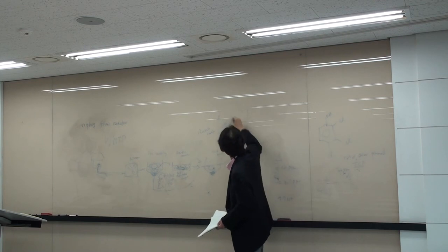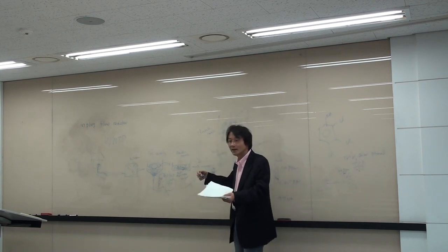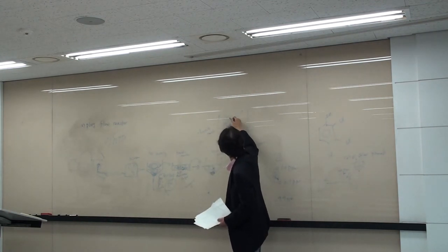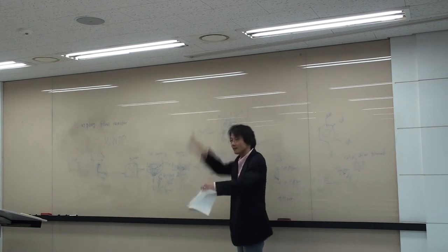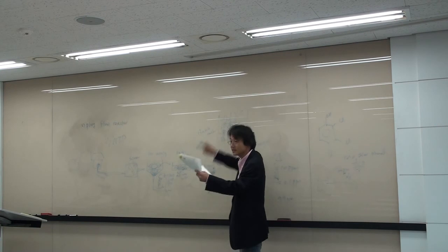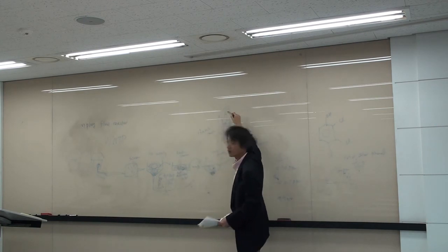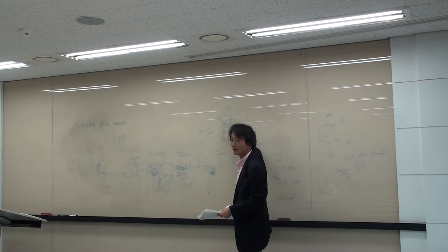Or you can put in a mechanical agitator, a kind of paddle on the surface. It is just like this, so it can agitate the water. The water jumps up and goes down, and it entraps oxygen, air, into the water.